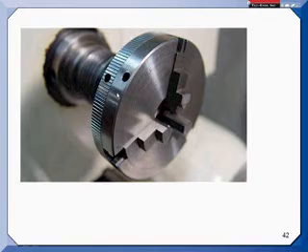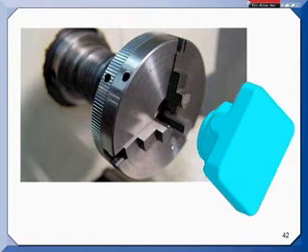In this case, we added 3 notches to that casting so that we can grab this on a 3-jaw chuck. The part will go in there and it'll mount up against these surfaces, and then we'll close in on the diameter with the jaws, and we'll use one of them to drive the part in the 3-jaw chuck.